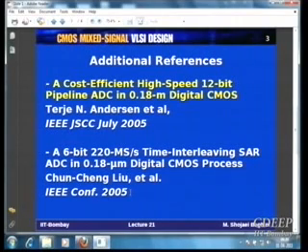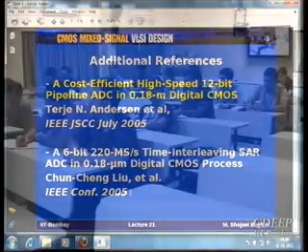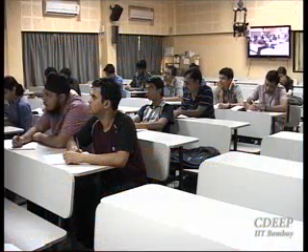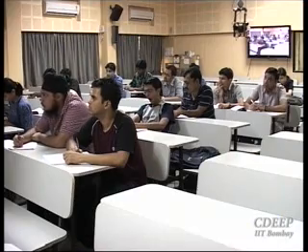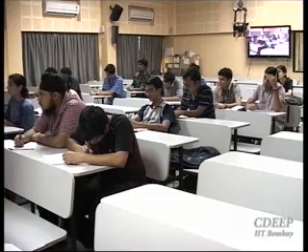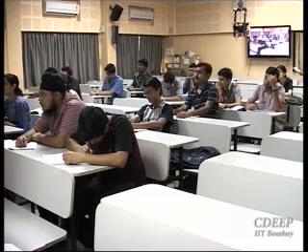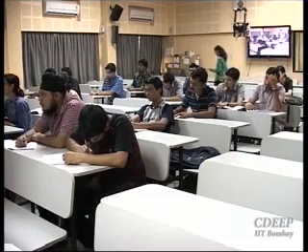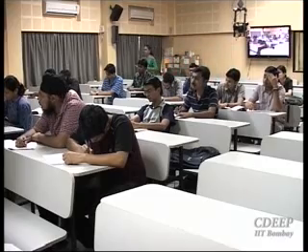So therefore, focus here will be examples. Okay, so what are the characteristics? First of all, it is 12-bit. Second, technology is 0.18 micron. It's a pipeline ADC, and it's cost effective because they have done it in a digital process.